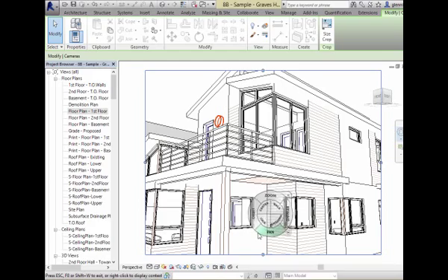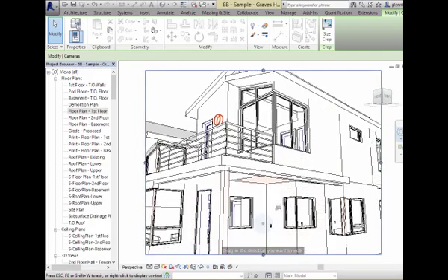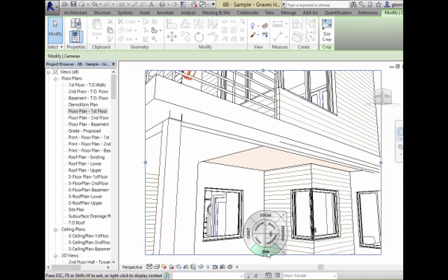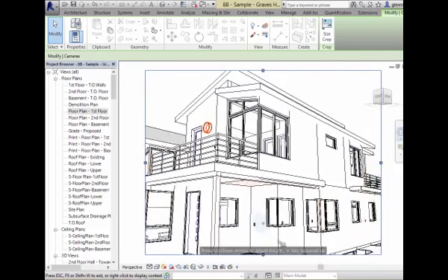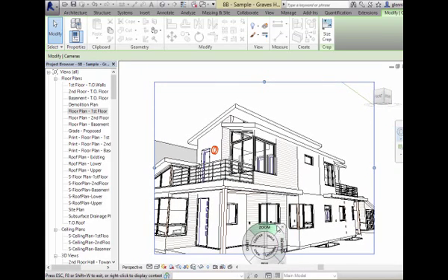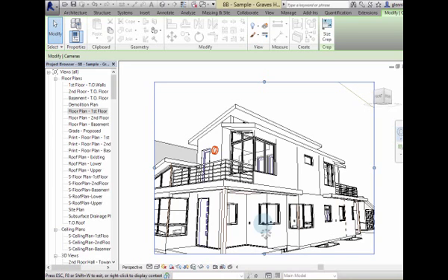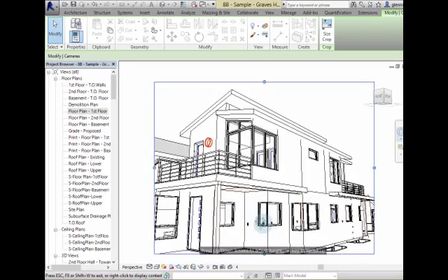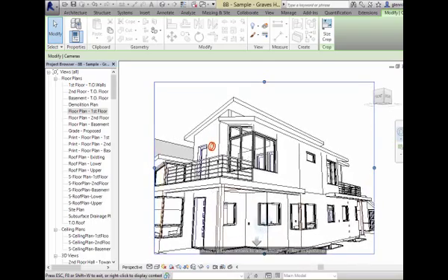So I'm going to choose the walk tool. I'm going to just walk it back slow. Oh, I'm walking in. No. How the walk tool works is, let me see if I can show you where it is. See that little dot in the blue? That is an indication of where we are. If you hold down behind the dot, I back up. If you hold down in front of the dot, you move forward. And how close you are to the dot controls the speed. So as I walk, oops, I'm rewinding. Okay, that's going to be almost dead still. If you move up, I'm moving a little forward. If I move back, I'm moving back a little.